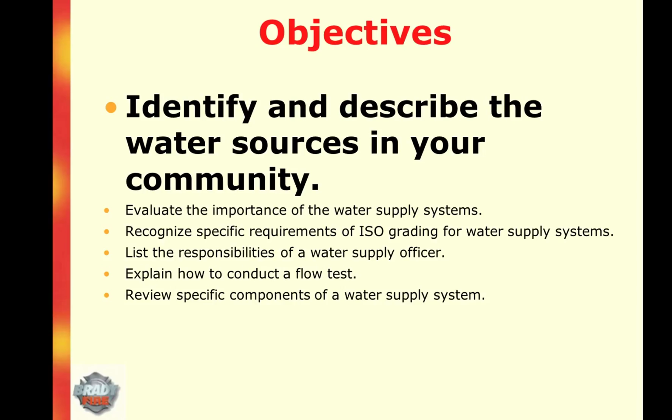Two general types of utility systems: gravity feed water systems and direct pump pressure water systems. The utility infrastructure includes water sources, filtration systems, distribution systems and storage systems, water towers, mains, pumps, chlorination plants, and fire hydrants. Utilities are normally publicly owned and operated through fees and tax collectors.